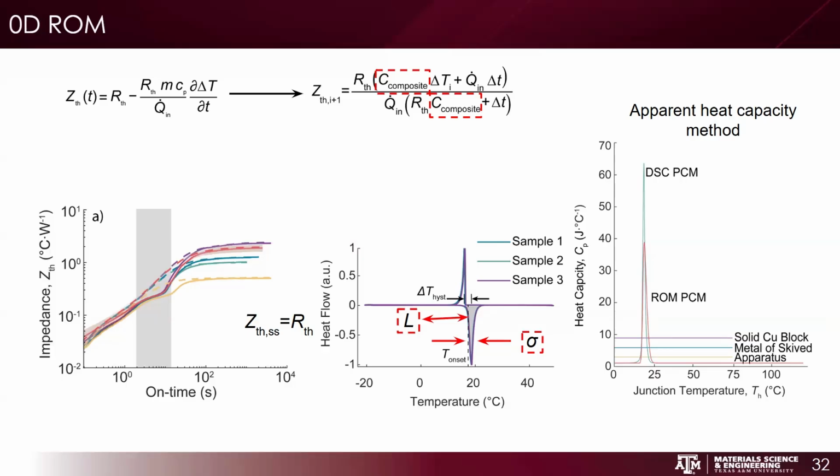I mean, what is the PCM here? Hexadecane. And if you go decimally slowly, 0.001 C per minute, would you expect a finite width to your peak, or would it be a delta function? I'm not the expert on the DSC, but there are two different models of the system. If you increase scanning rate, the onset of melting shifts. But I believe that this is one where, irrespective of scanning rate, the peak should be at the same point. You're talking about position, but what about the width?